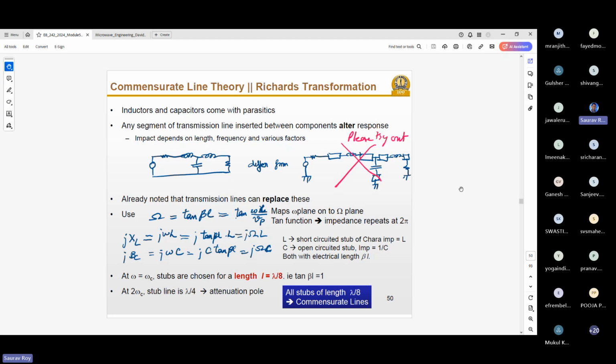But without that, can you just put the lumped element on a substrate? Can you solder it? No. Why not? There is also a solder mask placed on top of that, so it won't take the solder. So pads are placed so that after the design of the board, we can do the placement of the elements. Exactly. So here the hardware aspects come in.